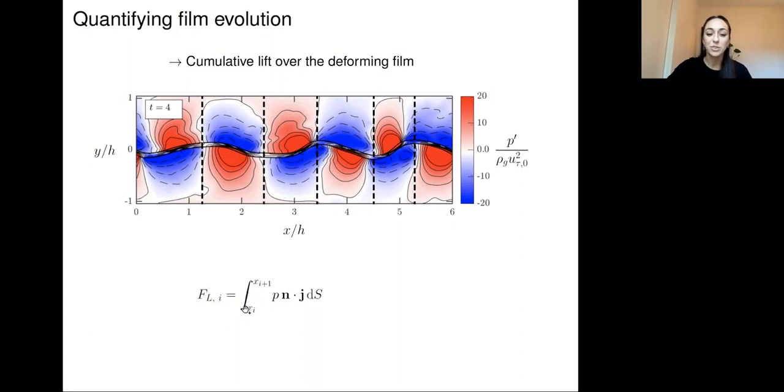And so if we were to, over each segment xi, just integrate that lift force, so the vertical pressure over the surface of each of these segments, and sum this up, what would happen is this would be roughly zero, because this problem is all symmetric in that direction. Now we can see that that's not a false picture, but that it's hiding what's really happening, because we can see these neighboring alternating highs and lows that are really tearing this sheet up. And yet if we just integrate this lift, we'll get only zero.